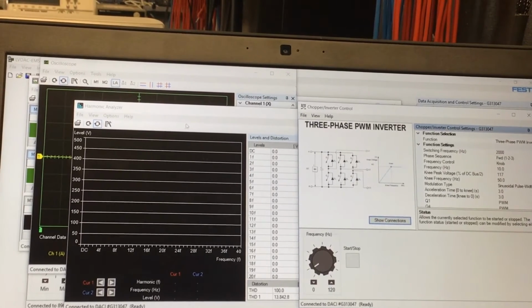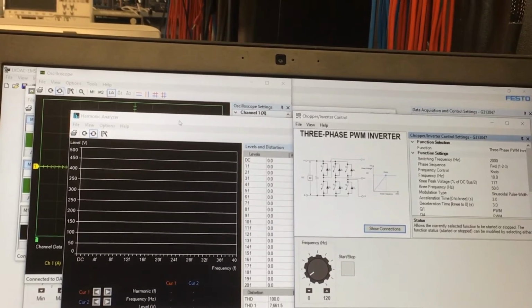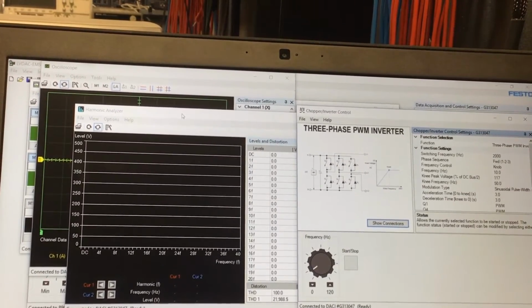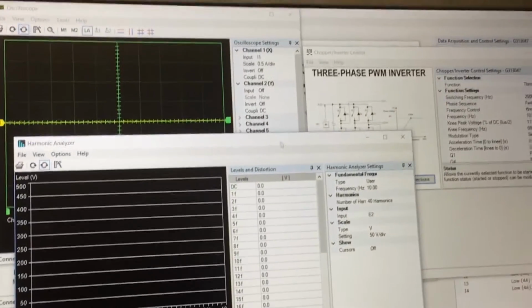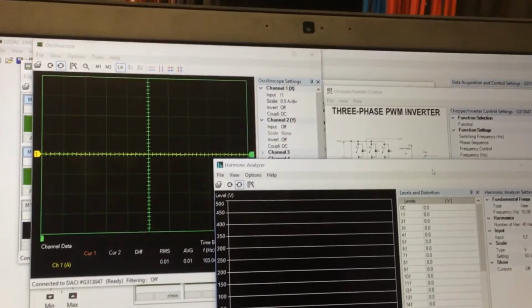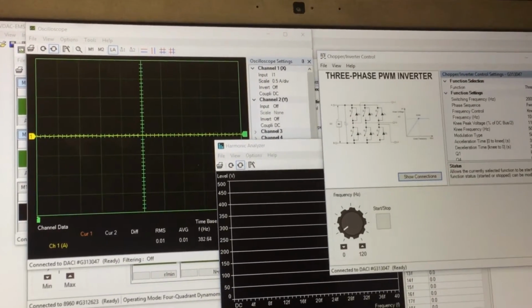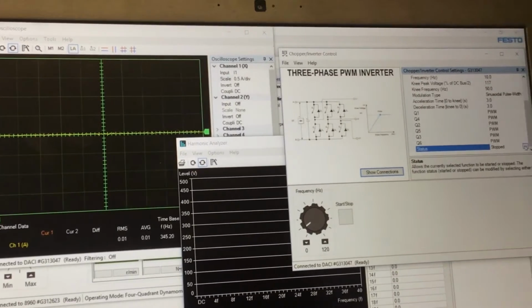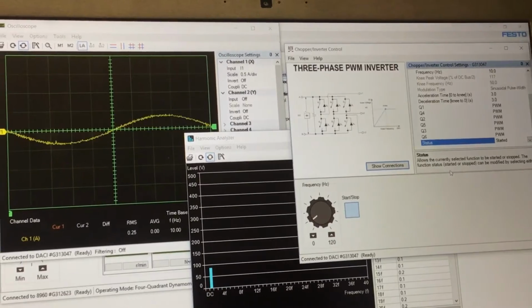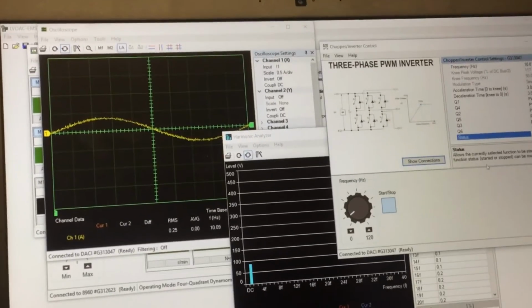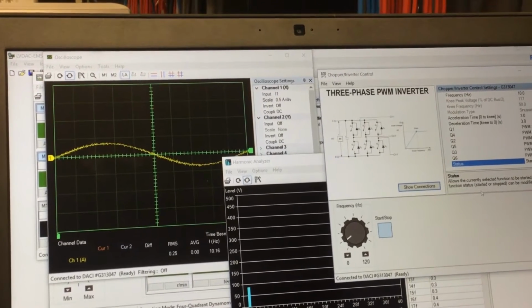And then because we need to monitor the harmonic, the voltage in the harmonic, and also the current from the oscilloscope, I try to show you all the details in one frame if I can do it here. Seems okay. What I need to do is run the IGBT from this point, and then we move to the output side. Okay. So we start with 1/5 of nominal frequency, which is 10 hertz.